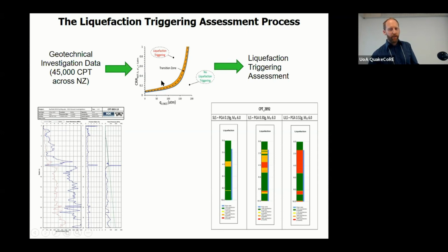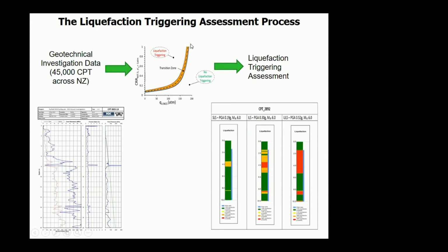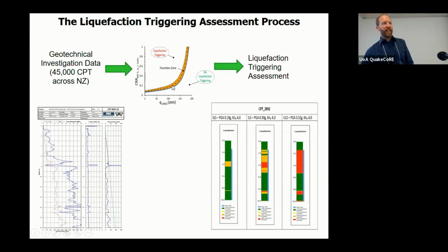Within that, there appear points of no liquefaction case histories occur on the left of the graph, and a few occur on the right-hand side of the graph. So it is an empirical based equation that has been set. It just is that when you're sitting near that boundary, there can be a little bit of under and over prediction. The further you are away from these boundaries, the better your prediction should be.